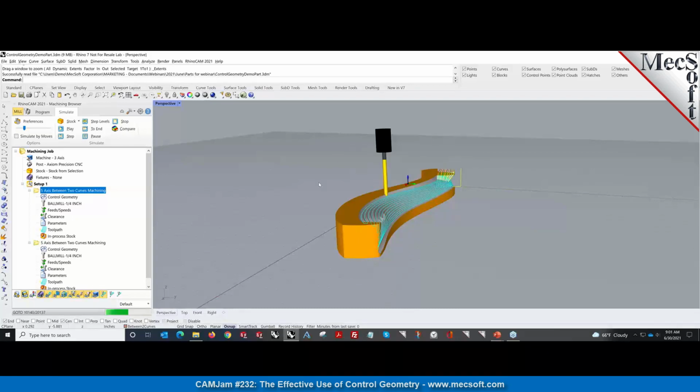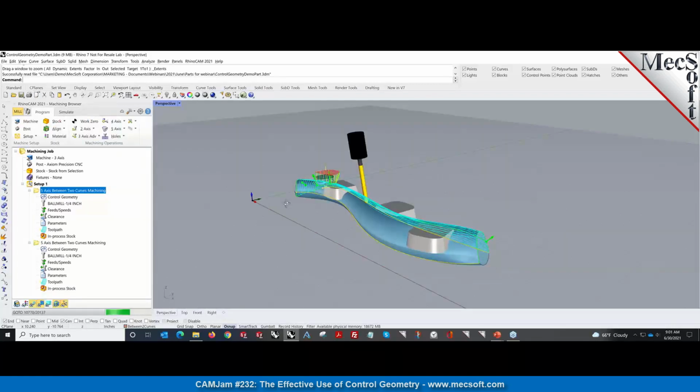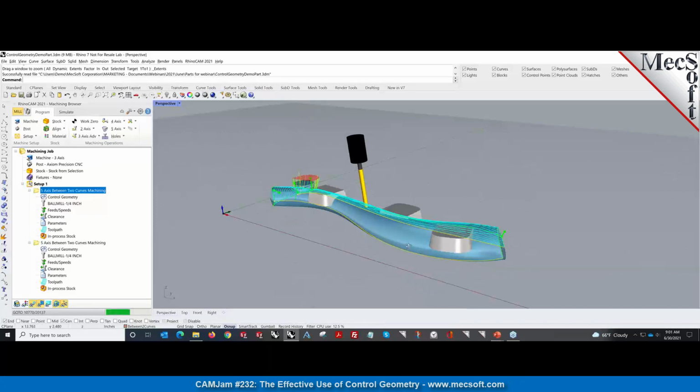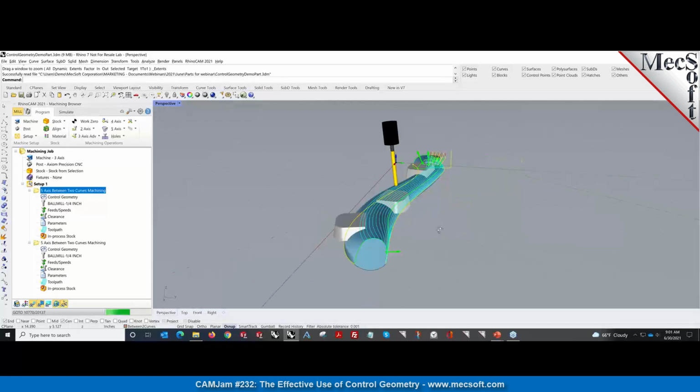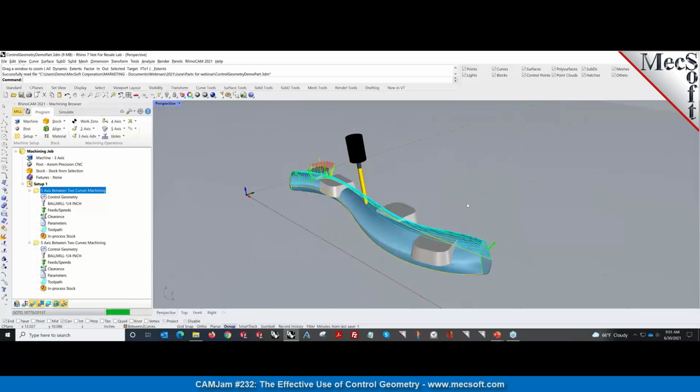In index machining, what we are doing is different. We are locking a particular axis. We are rotating the tool axis. Let's say we're doing an index machining. We're coming in from this direction. And we're locking that tool axis in that orientation, not position, just that orientation. And then machining in 3-axis mode. So that is what index machining is, as opposed to continuously varying the toolpath method in 5-axis.